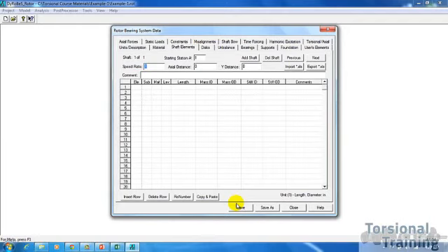And in order to start that, you first develop your element. So in this case, we're only going to need one element, since we're just trying to check the torsional inertia and the torsional stiffness calculated by Dyrobes, and we're then going to go ahead and compare what we calculate with respect to a hand calculation. So without much further ado, under the element column right here, click there and hit element number 1. So this is the first element, so it'll be element number 1.